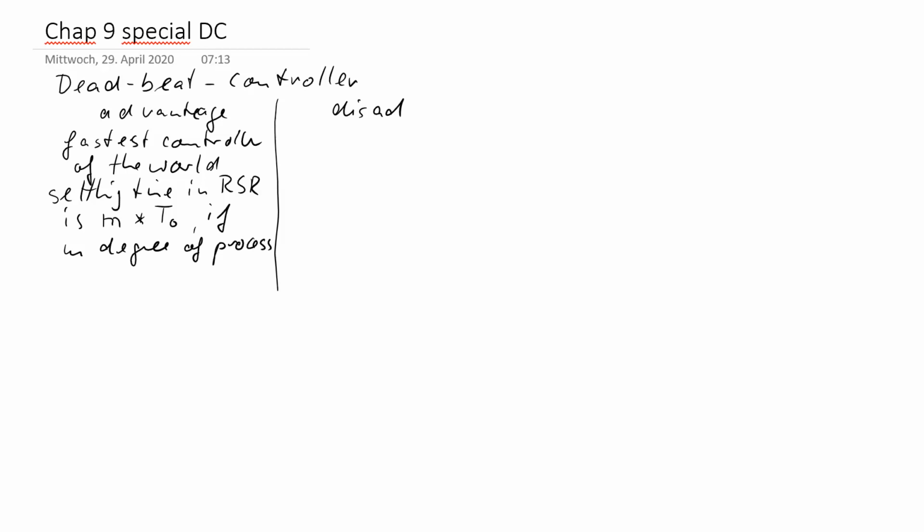Of course, in a PT1, less than 1 step is not possible, but in a second order system, there is no control procedure thinkable which does this in less than 2 steps. So I think this is an interesting theme. So we should work on this principle, learn something about it, and then we can talk about disadvantages, because if you look into the realized controllers in industrial applications, you cannot really find a deadbeat controller.